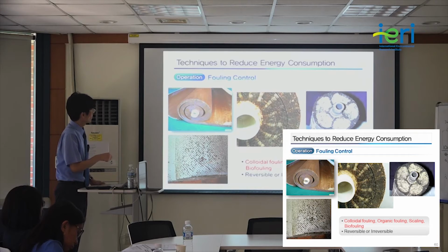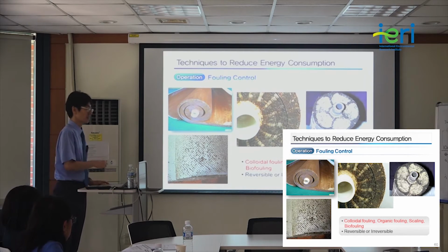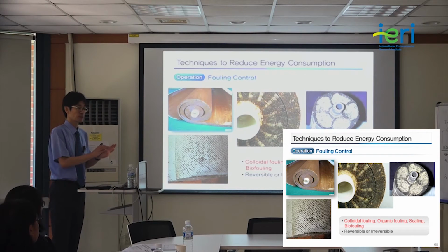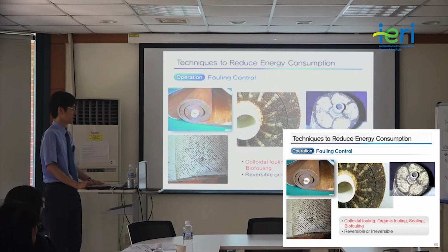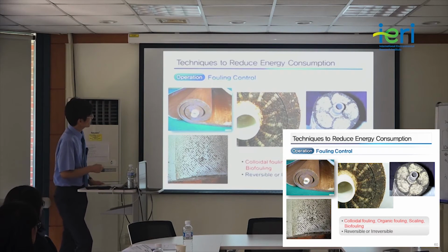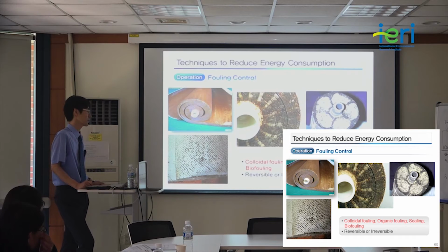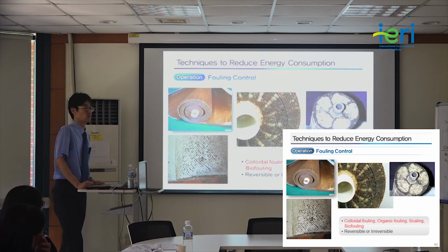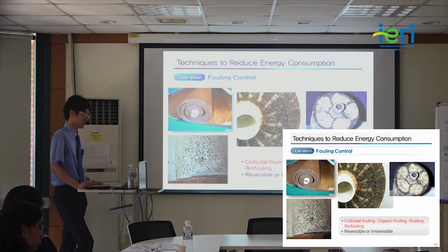And this is the so-called spacer inside the membranes. The basic goal of the spacer is to separate the membranes and guarantee the feed channel or permeate channel. But when fouling happens, this spacer can be blocked by this inorganic or organic foulant, so it cannot work anymore, so that again this will significantly reduce the efficiency of the original membrane.